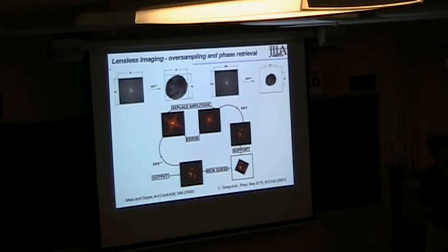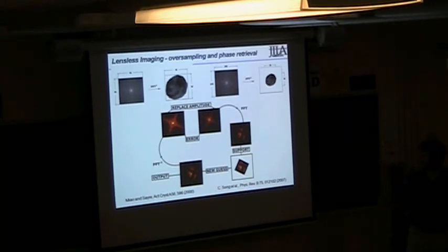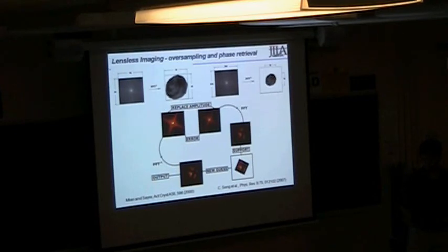Okay. What's a typical sample for your transmission experiments? Metal, dielectric, or semiconductor? So for instance, this sample is lithography etched gold on a silicon nitride window. Can the silicon nitride window be very thick? It depends what wavelength we're using. Actually, at the 13 nanometer wavelength, it's relatively transparent, so we usually use 100 nanometer thick.